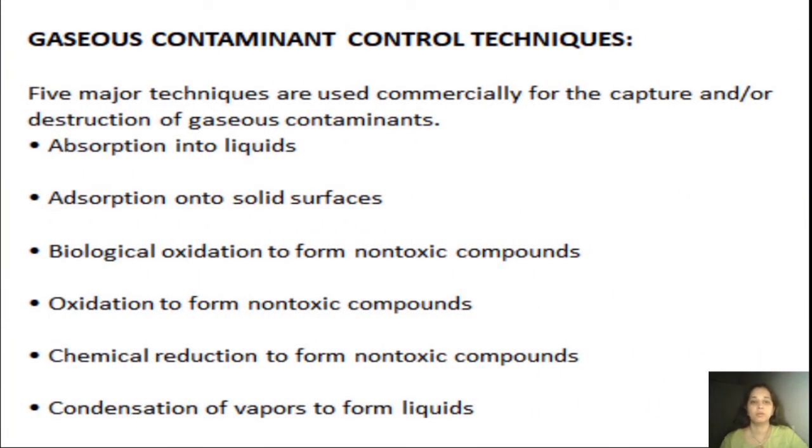Gaseous contaminant control techniques. There are five major techniques which are commercially used everywhere globally. The first among them is sorption, that is, adsorption or absorption technology. So absorption into liquids, where you would have your scrubbing liquids or scrubbing liquors, and adsorption onto surfaces.